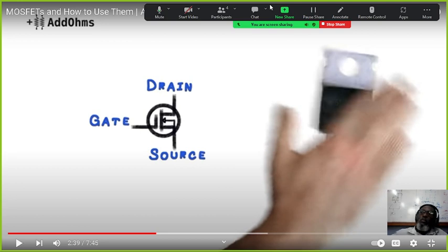Voltage is straight out. The FET. All FET. Whether it is JFET or MOSFET, all FET use voltage to turn it on at the gate, or to control the current between the drain and the source. So to control the current between the drain and the source, at the gate you have to use a voltage.